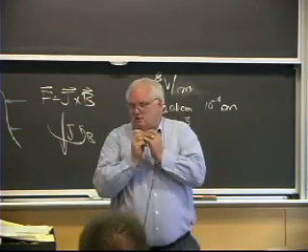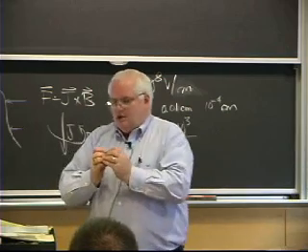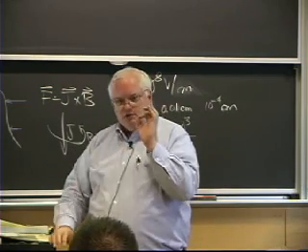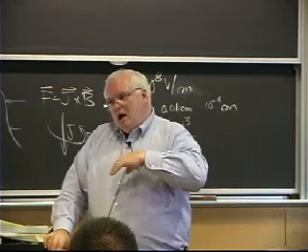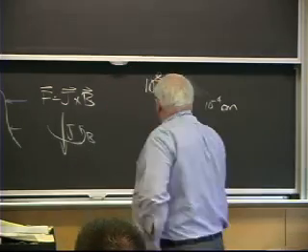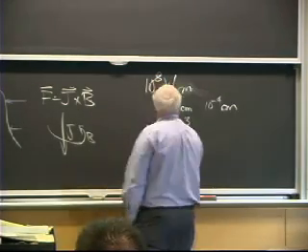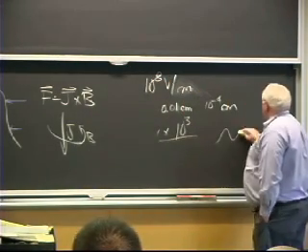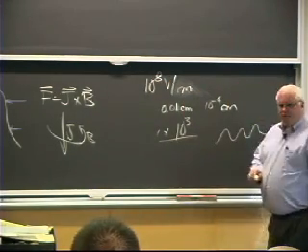And if I actually get a little bit closer, and if I have several thousand volts, then essentially field emission, when I get down to something less than a human hair apart, I'm basically using field emission to strip the electrons out of there. It turns out the reason I actually get that extra factor of 10 is the surface of the solid is slightly rough.